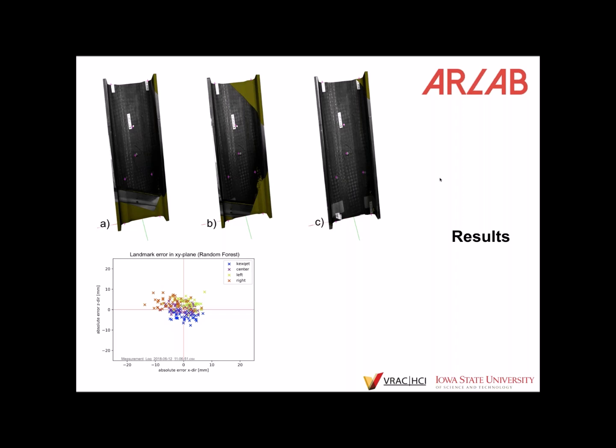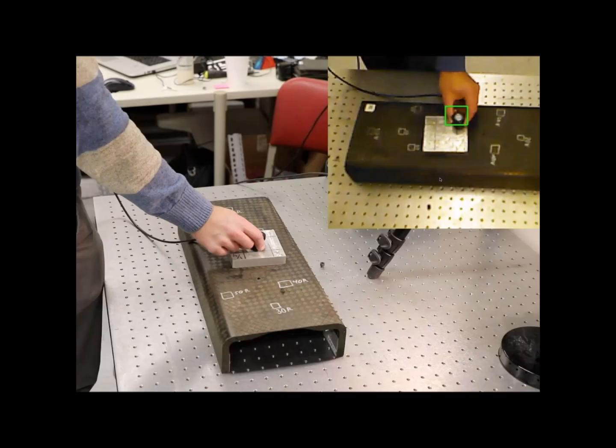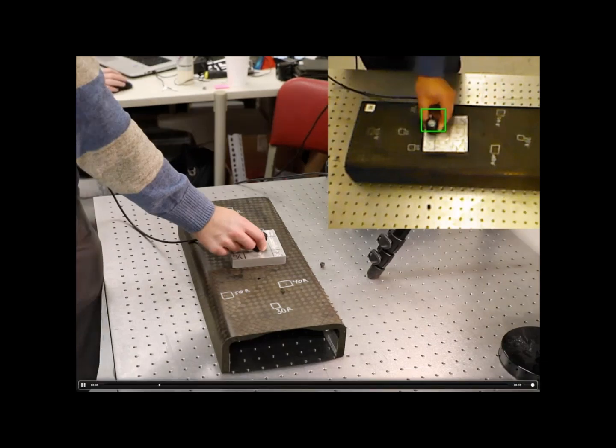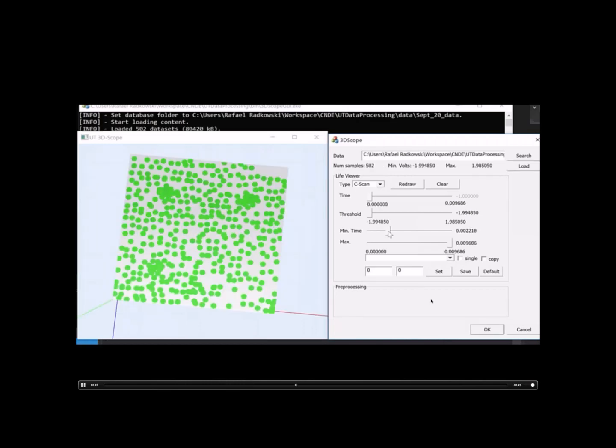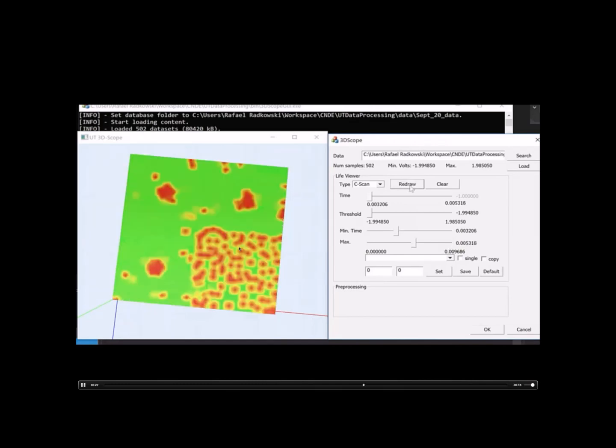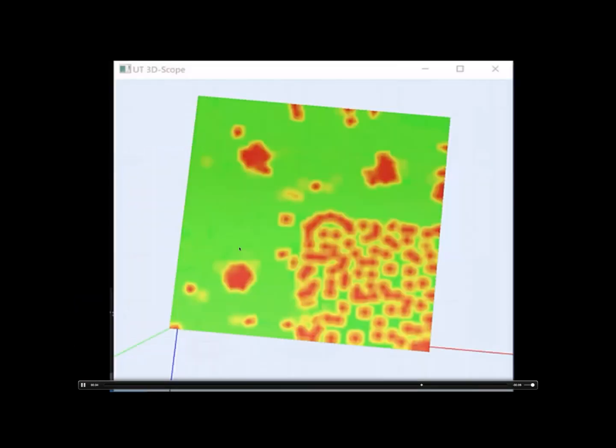You see here we track an ultrasonic transducer in 3D, so there's a point cloud behind this. A calibration specimen, because we know the flaws on the calibration specimen, bore some holes and a cutout. Those points that we see here are the measurement points. We just measured points, so we cannot really paint everything right now. It's just how our ultrasonic inspection technique works. So somebody has to press the button all the time and say record data, record data, record data, and then the scope writes everything into a file.